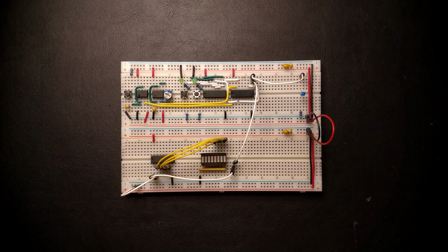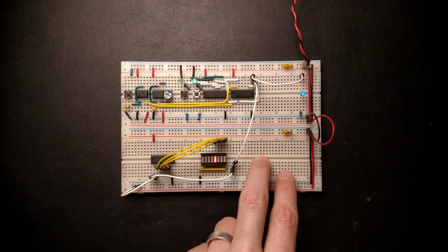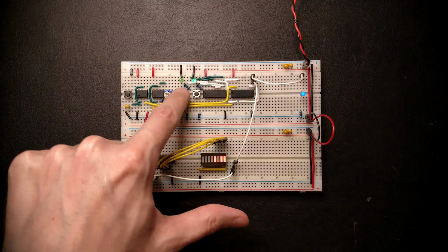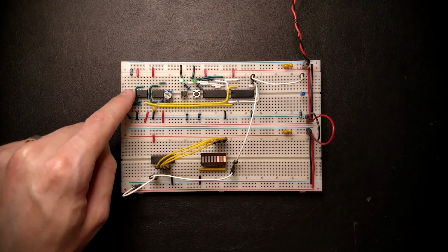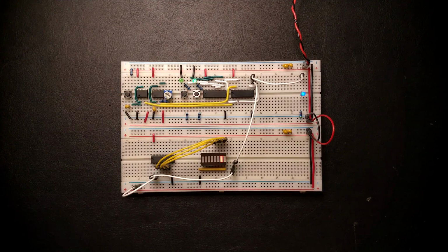In the previous episode, we finished building up the clock selector and multiplexer on the breadboard. This now allows me to put the clock generator into a single stepping mode where we can trigger individual clock cycles manually, and the free running mode where the clock just runs at a tunable frequency. Those clock modes will be vital for debugging the Superscalar out-of-order processor as we start to design and build it.